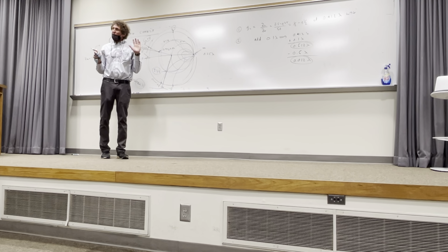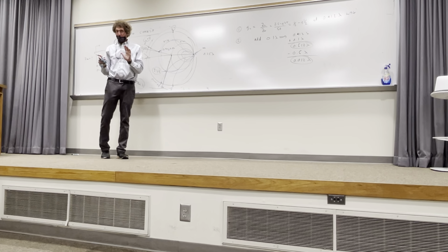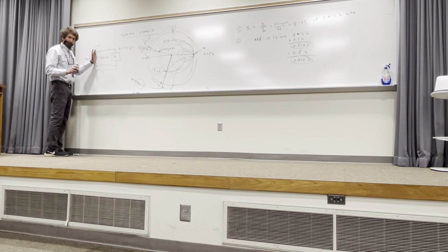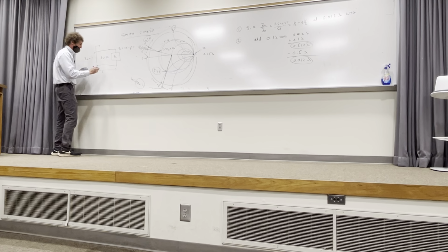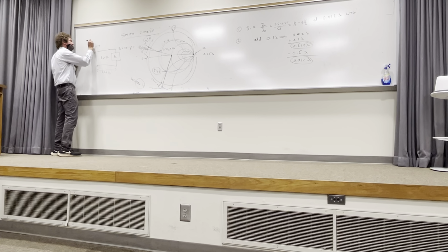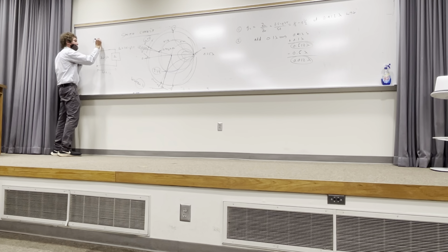If you want the actual input impedance, that is the normalized input impedance, all right? To get the actual input impedance at this point, because this is where we moved a tenth of a wavelength, Zn itself would be equal to the normalized Zn that we got from there times Z0.